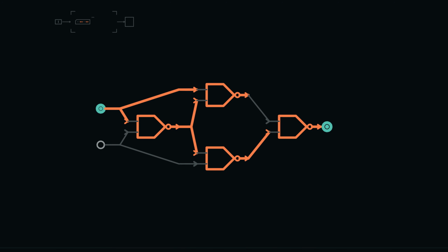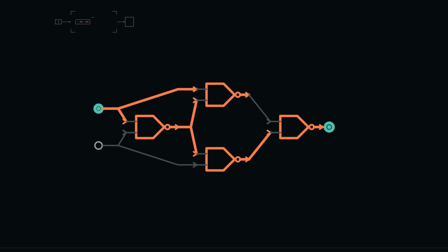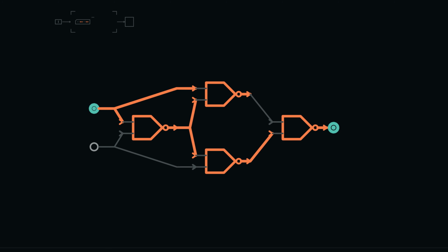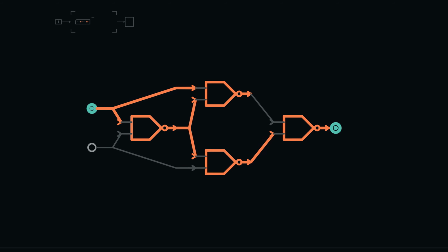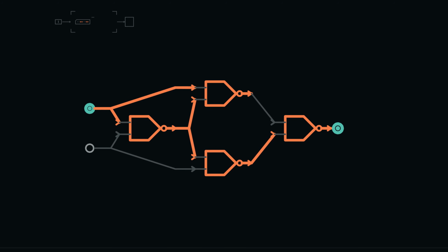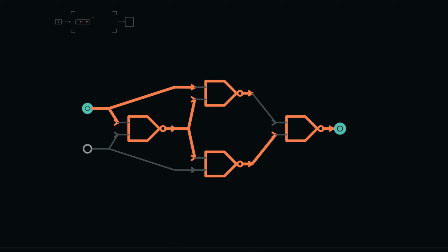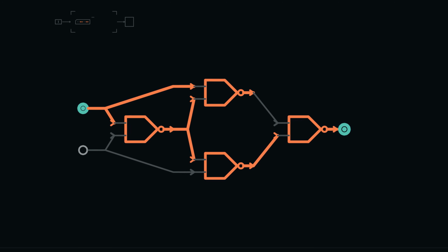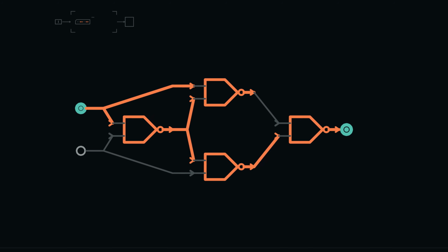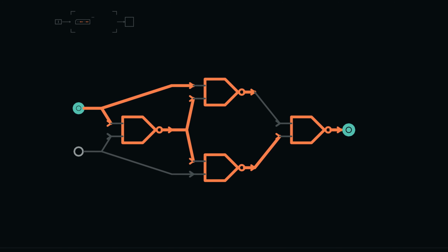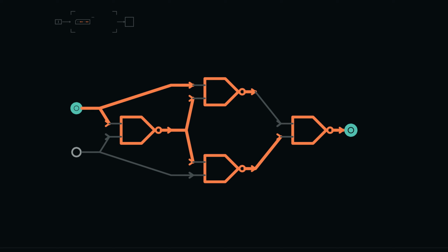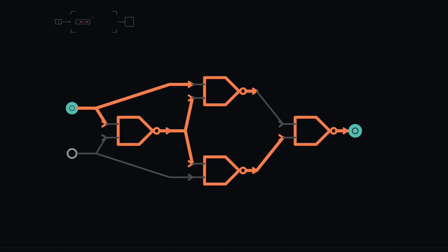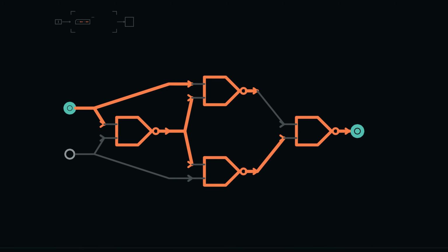In the abstract table, intermediate values appear in logical order. In a physical network, each gate has propagation delay. 2 routes with different numbers of stages may settle at different times, so an output can briefly pass through a value that is not the final stable answer. Later, timing rules will tell storage when it may safely capture a result. Our diagrams therefore distinguish a route that is changing from a value that has settled. Instant, perfectly simultaneous motion would make the picture easier and the explanation false.